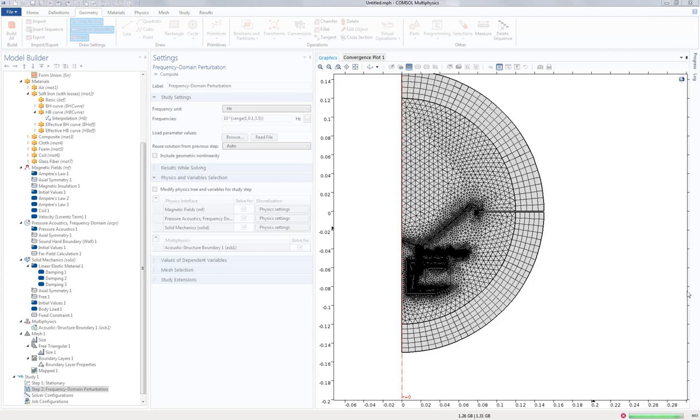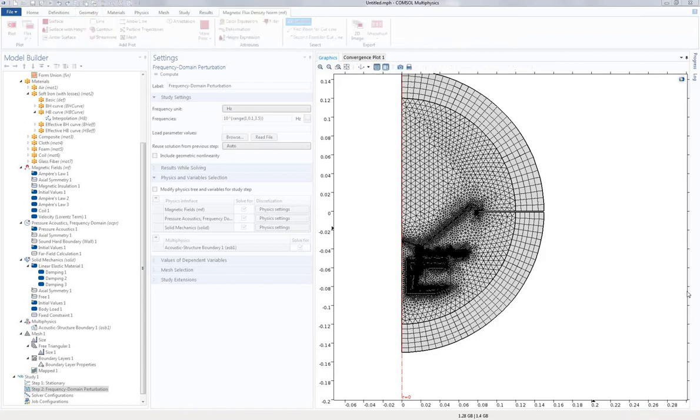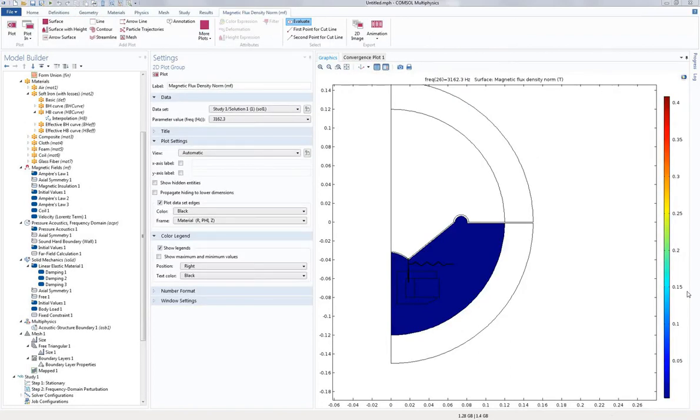Since the working fluid of the thermoacoustic device is a helium medium, this triples the speed of sound, therefore should affect the pressure velocity of the standing wave. Yes, indeed. If you switch to helium, you will get a different speed of sound. That's automatically going to work itself out.